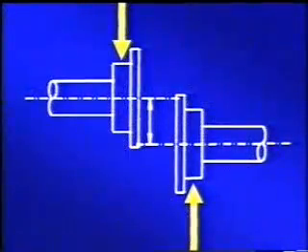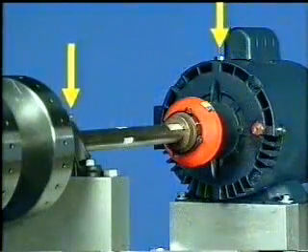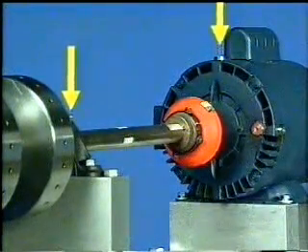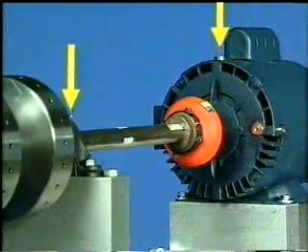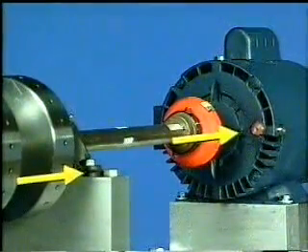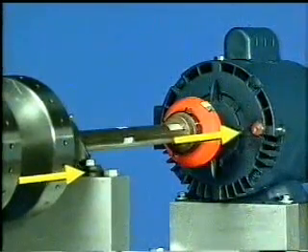When shafts have an offset misalignment condition, the coupling pulls one shaft one direction, and the other shaft the other direction radially, forcing them to match up. This condition produces a 180-degree phase shift across the coupling in the vertical or horizontal directions. The axial readings across the coupling are in phase.